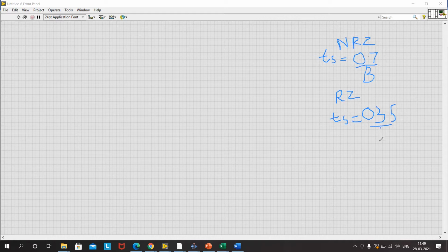Good morning, everyone. We are going to perform the rise time budgeting. We know that the system rise time for non-return to zero is 0.7 divided by the bit rate. And for return to zero, the system rise time allowed is 0.35 divided by the bit rate or the bandwidth of the receiver.